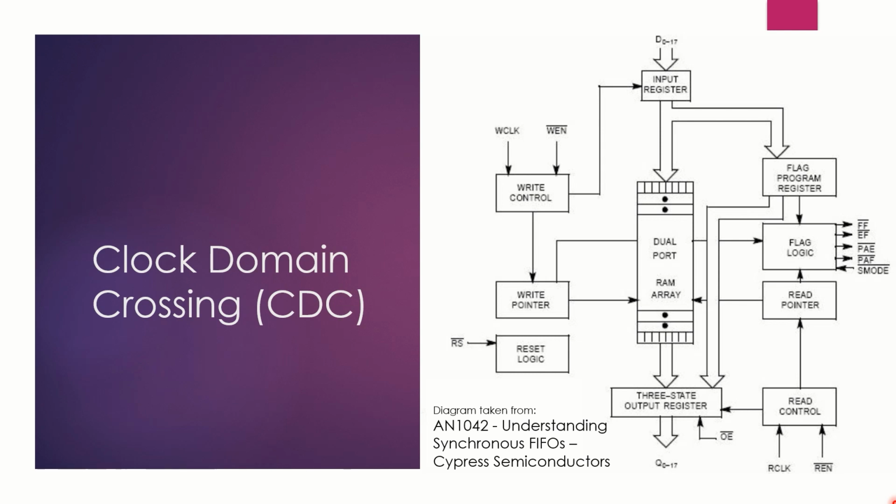Synchronous FIFOs also offer many other advantages that improve system performance and reduce the complexity of circuits. Synchronous FIFOs are easier to use at high speeds because they use free running clocks to time internal operations, whereas asynchronous FIFOs require read and write pulses to be generated without an external clock reference.